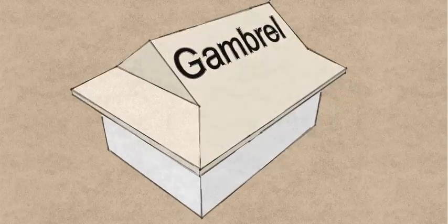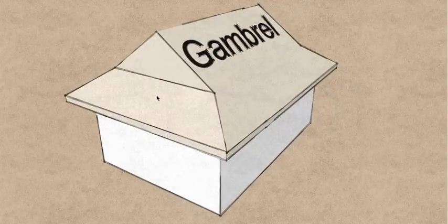And the other one, which is similar to a Dutch gable, and they're quite often called Dutch gables, is a gambrel. Gambrel is basically got half the height of the roof as the gable end, and half the height of the roof as the hip end. And this is the one I was talking to my American friend about. They call that the mansard I'm about to show you. They call that a gambrel.